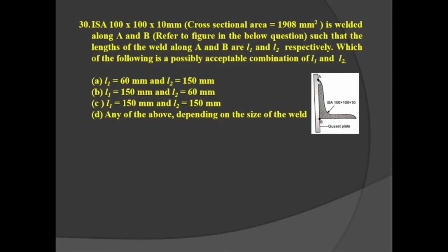So my dear students, if I make the diagram of this particular cross section, here the welding surface is L1, and here the welding surface to the gusset plate is L2. This is our gusset plate. We have to calculate these lengths L1 and L2. Here longitudinal shear plays an important role, P1 and here also P2. This is the type of problem of a moment free connection.